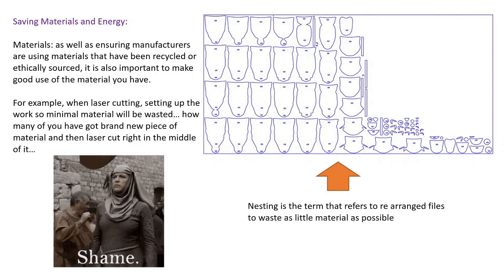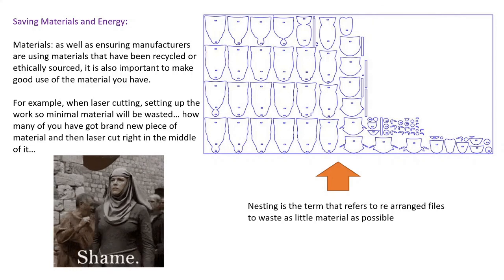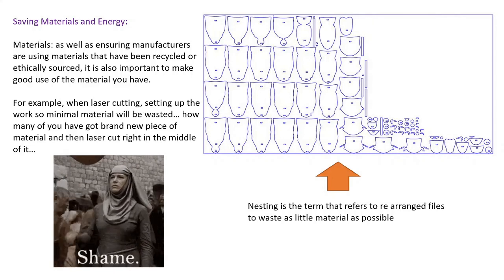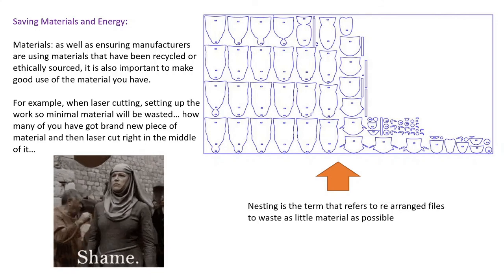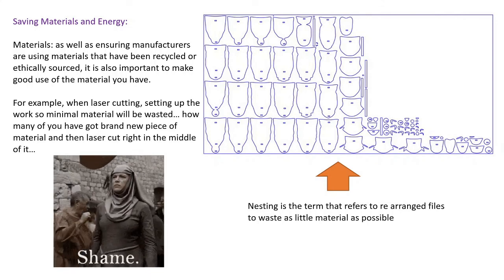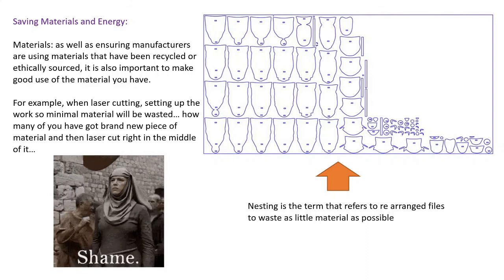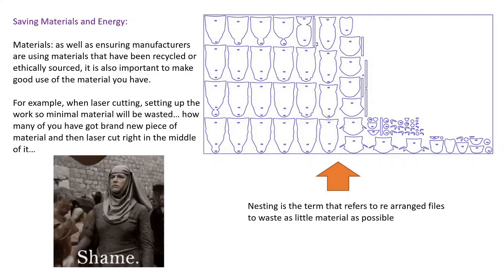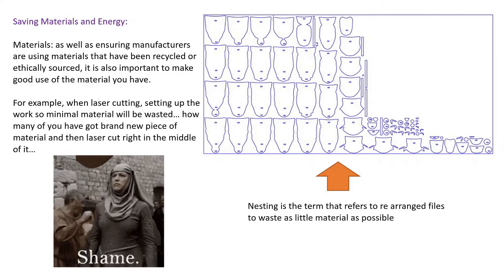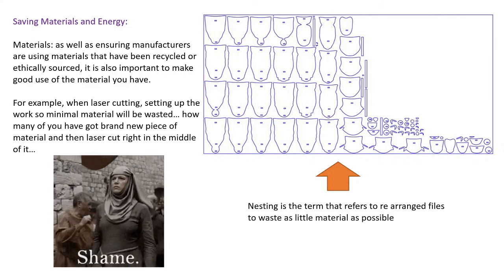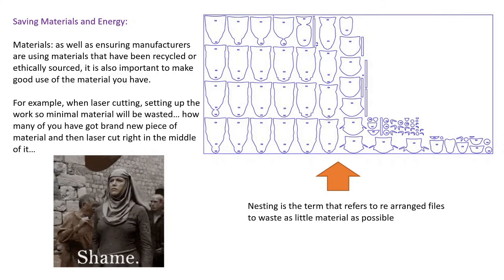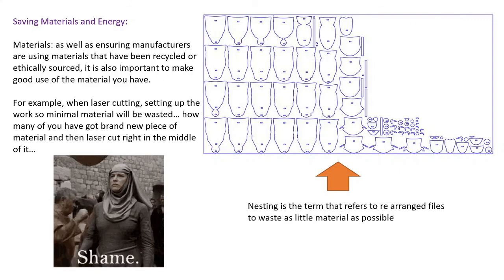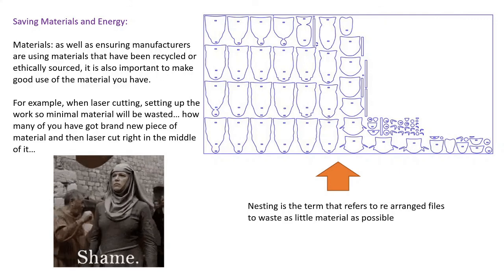But because companies are paying and they want to make sure they're not wasting material, it's called nesting. If you can see the diagram on the right hand side, all of those drawing files could easily have just filled up that whole page. Quite easy, I've seen students do that all the time. But just by arranging it and making things as close as possible, you've got a whole other usable piece of material left. So just be aware that the term is called nesting, and it's about making sure you're not wasting any excess material when you don't need to.